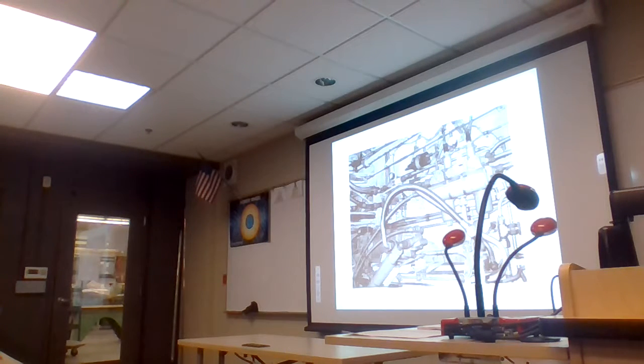Picture of, I think, also a DC-8 or a DC-9 aircraft. This is a filter module, and we usually have pressure and return filters located in the same location that provides for servicing. Sometimes we have the outlet of a pump. You might have a filter on the pressure line. The return line that leads back to the reservoir will also have a filter, but it makes it kind of easy to service both components, the filter elements, at the same time. So they have everything incorporated into a filter module.